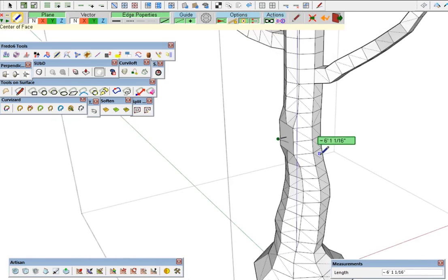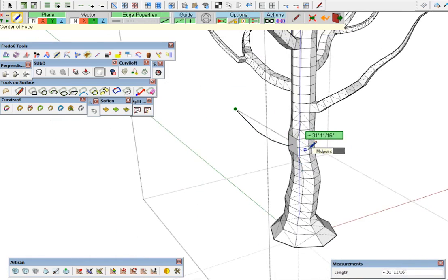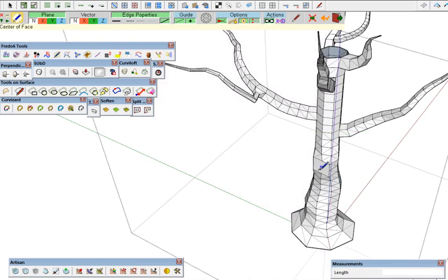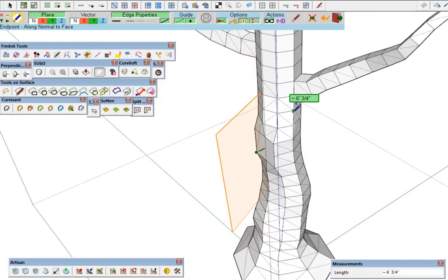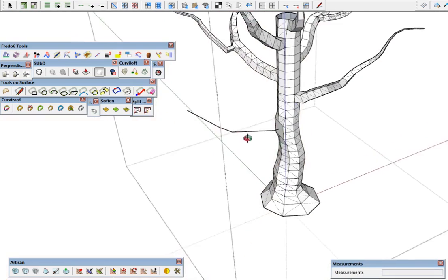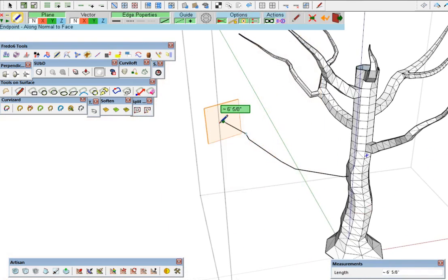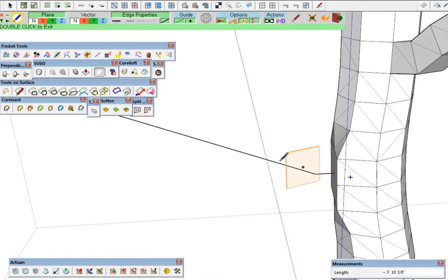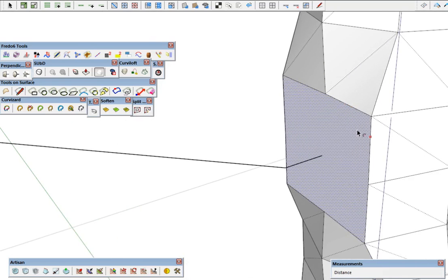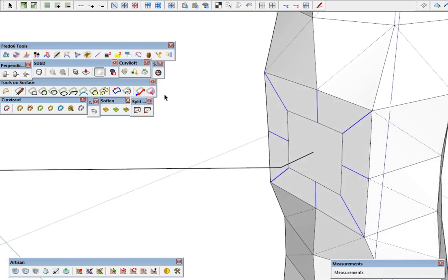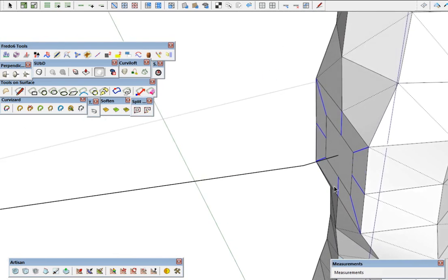Now we can come in here and set our work plane. Offset that. It looks a little bit too extreme there, and just connect these, or also use split tools here. We can just select that whole face, and that'll go around and make all the connections there that we need to keep this good quads.